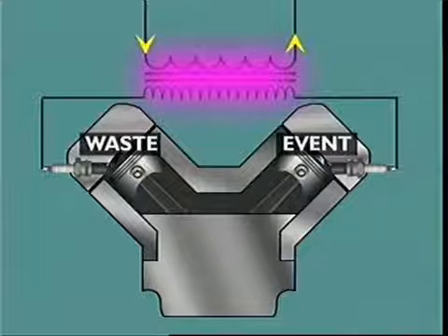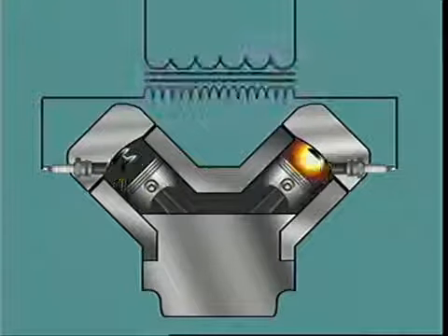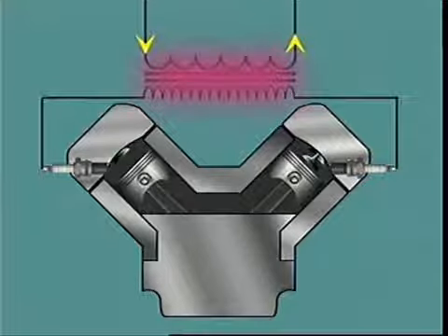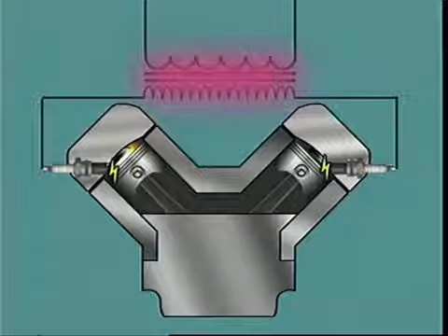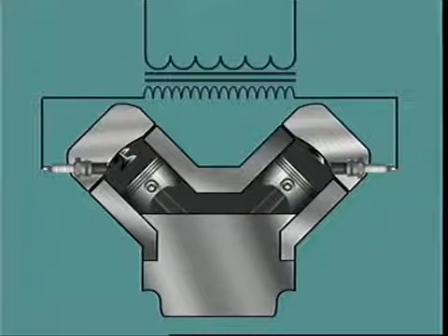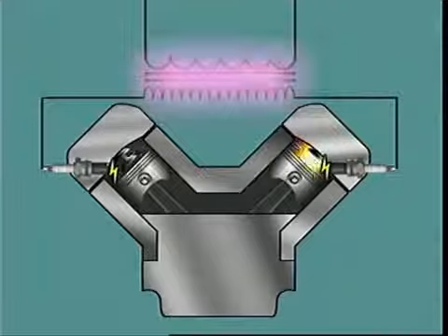the event cylinder. Firing of both plugs again takes place, and this cylinder now drives its piston down on the power stroke. This same process occurs on each pair of companion cylinders as they approach the top dead center position. Triggering of the primary circuit in each coil must therefore occur at the correct time in each crankshaft revolution.